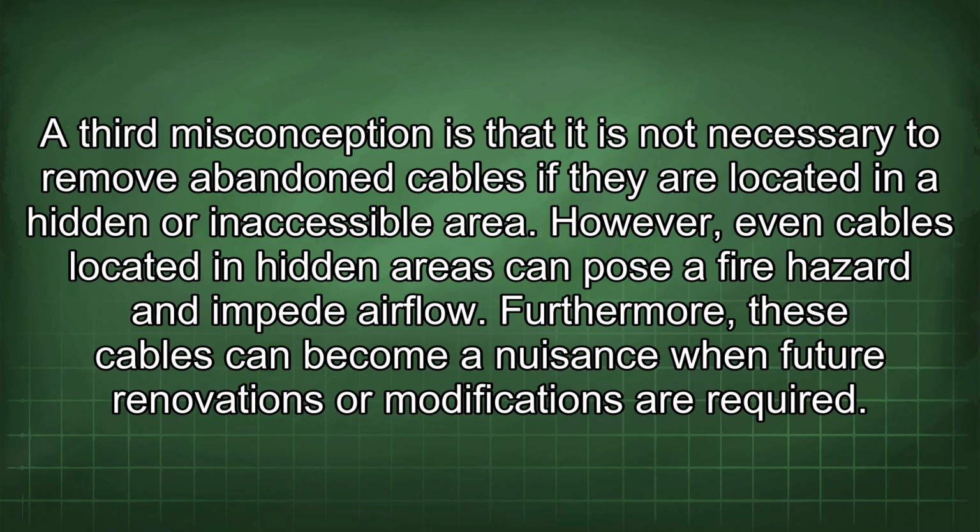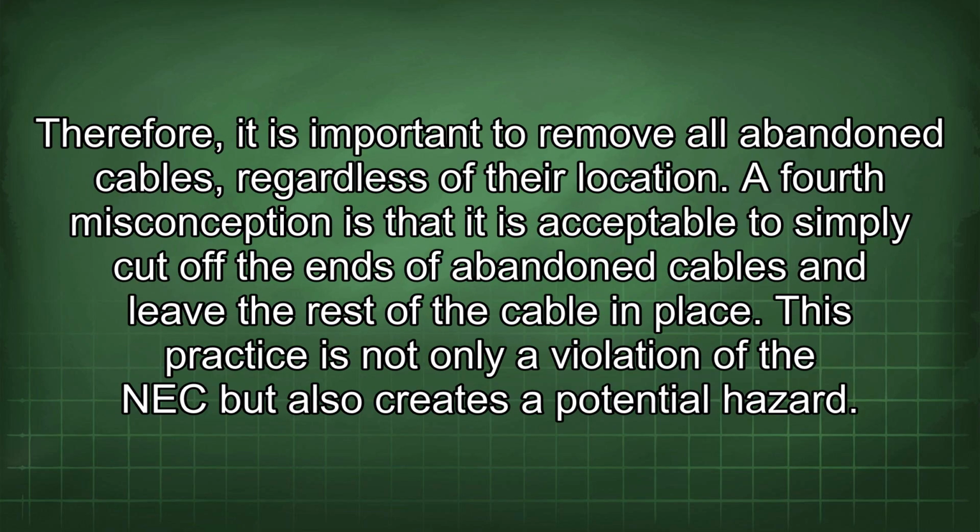A third misconception is that it is not necessary to remove abandoned cables if they are located in a hidden or inaccessible area. However, even cables located in hidden areas can pose a fire hazard and impede airflow. Furthermore, these cables can become a nuisance when future renovations or modifications are required. Therefore, it is important to remove all abandoned cables, regardless of their location.